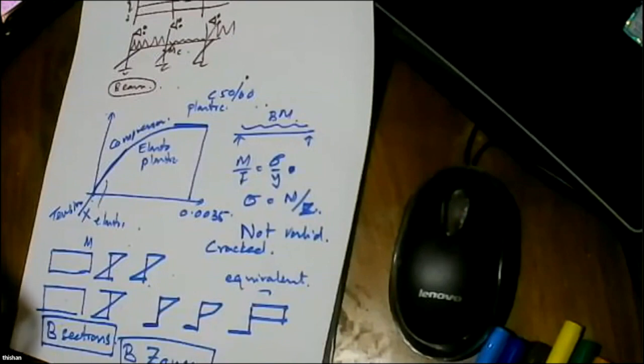For example, a 1200 pile can usually carry a 6500 kilonewton load, but it is now carrying only 4200. A 1500 pile can generally carry 10,500 kilonewtons, but on this particular site it can carry only 6,500 kilonewtons when you do all the calculations according to the geotechnical engineer.